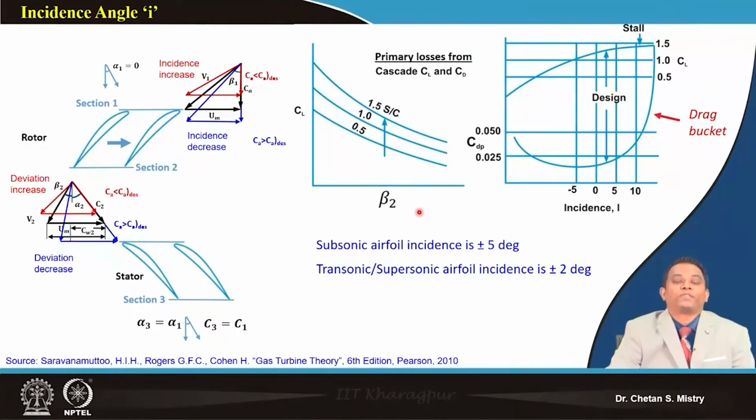So if you look at, say, NACA 65 or when we are looking at a C4 kind of aerofoil, their leading edges are thicker, and that is little insensitive to the change of incidence angle, and that's the reason why this is giving us flexibility of variation, or that can tolerate plus or minus 5 degree.